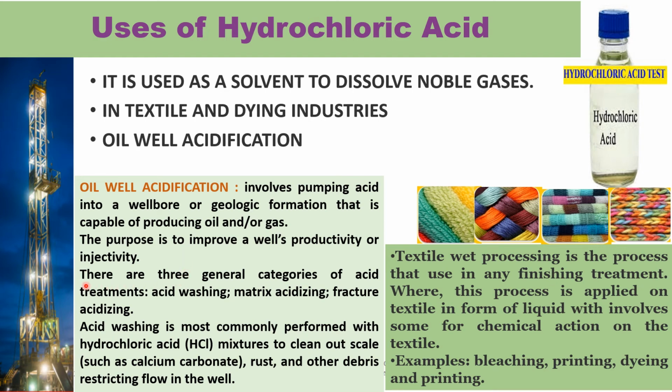There are three general categories of acid treatments: acid washing, matrix acidizing, fracture acidizing. Acid washing is most commonly performed with hydrochloric acid mixtures to clean out scale, such as calcium carbonate, rust, and other debris restricting flow in the well.